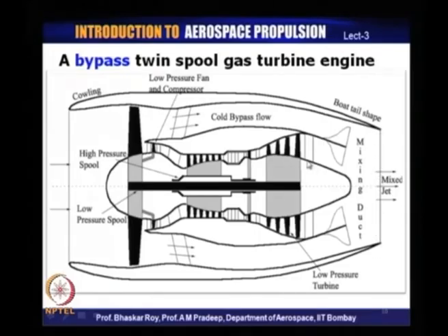Now, this is very important, and hence the design of this nozzle system over here, all the way from here, the shaping over here is extremely important in terms of aerodynamics and the gas dynamics, because at the exit face right over here, we want absolutely uniform temperature and pressure profile,